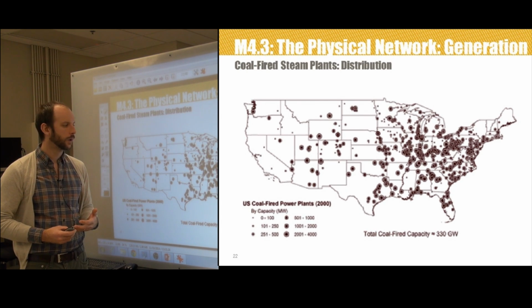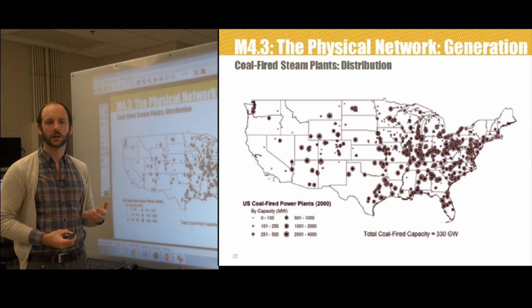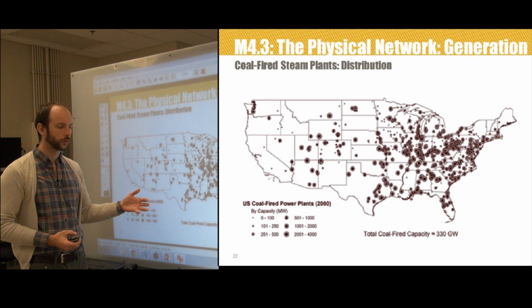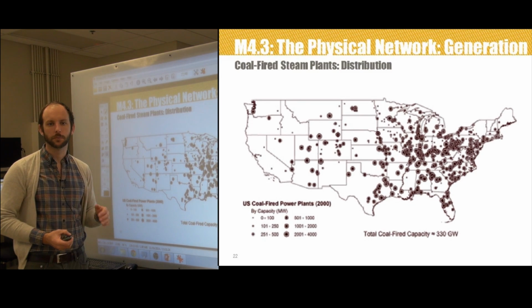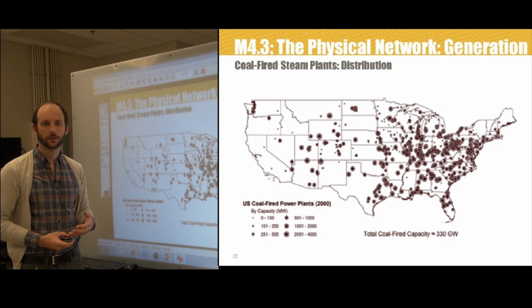Older units, we didn't have the engineering technology to build them as large, so they tend to be smaller than that. If you look at the market for where coal technology is going, current life extension capabilities are probably going to extend the average lifespan another 30 plus years. Those older technologies, those smaller plants, are probably below 30% efficiency. Newer technology is about 36%.